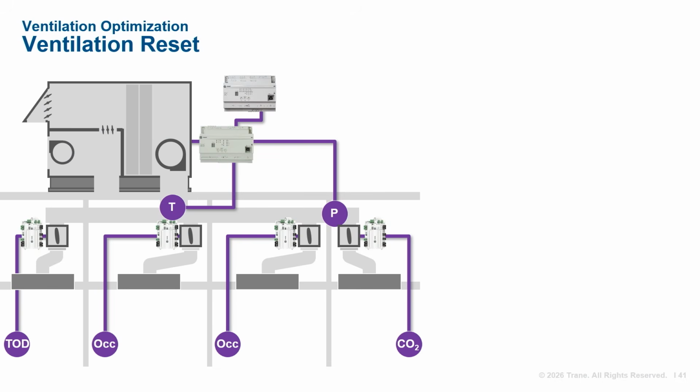Now, with the current occupancy levels determined, the system can calculate the required breathing zone outdoor airflow rate for each zone. Remember, the VAV box flow ring continuously measures primary airflow being delivered to the zone, so the VAV controller can calculate the real-time outdoor air fraction. Next, the standard 62.1 system calculations can be computed to identify the system ventilation needed. This is the system-level calculation commonly called ventilation reset.